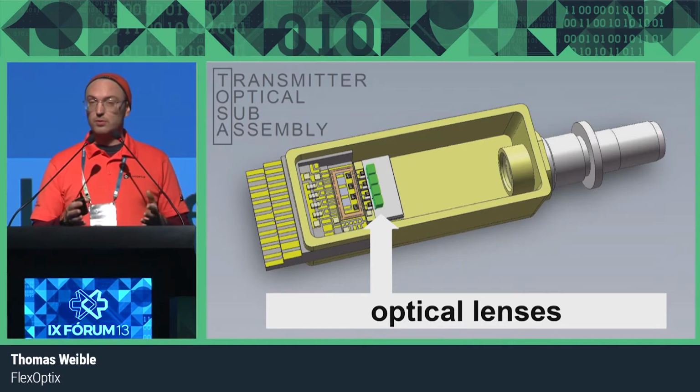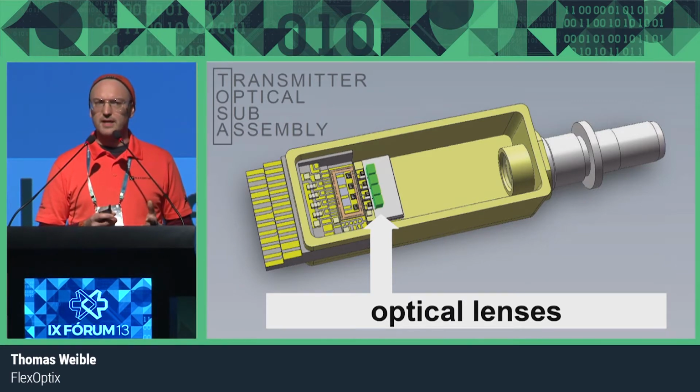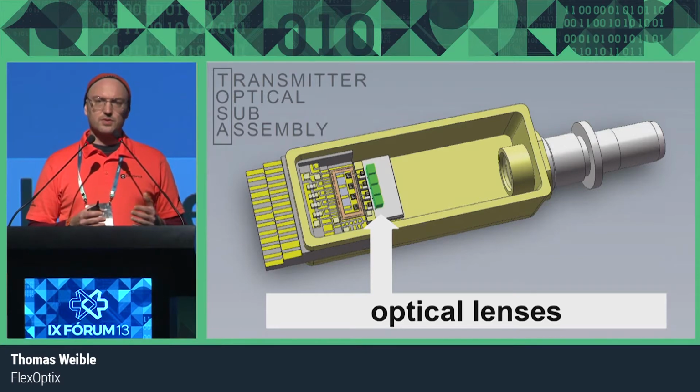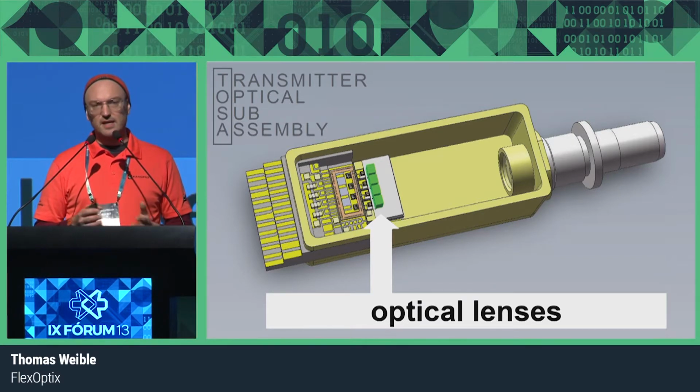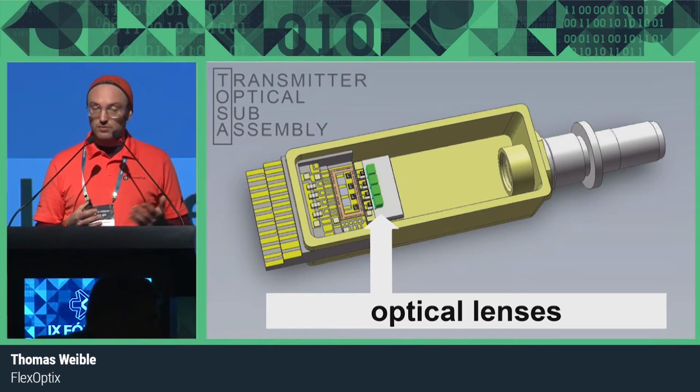You have to imagine this golden box has a size of 5 by 10 millimeters, the overall box. Now these tiny lenses in there have a dimension in XYZ of 0.5 millimeter, pretty small actually. And in the production process, you have to place them in XYZ. This is done with micromechanics in 50 nanometer steps. And then the second challenge happens. You need to fix them there to stay there for the next years and decades during operations.